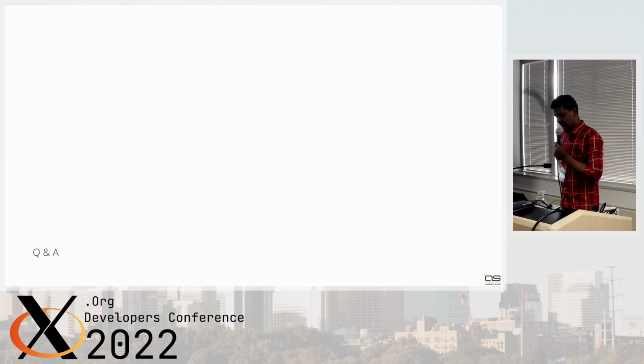To answer that, the display switch itself is a bridge, so we have bridge operations. Right now, what I'm doing in the bridge operations is that when the user attaches the HDMI, I get an interrupt. So HPD is on, and if HPD is on, I will change the bridge chain. If the bridge chain is changed, the DRM bridge will recollect the bridges again. One of the functions in the bridge operations is enable and disable, and that is where I'm enabling and disabling the lanes.